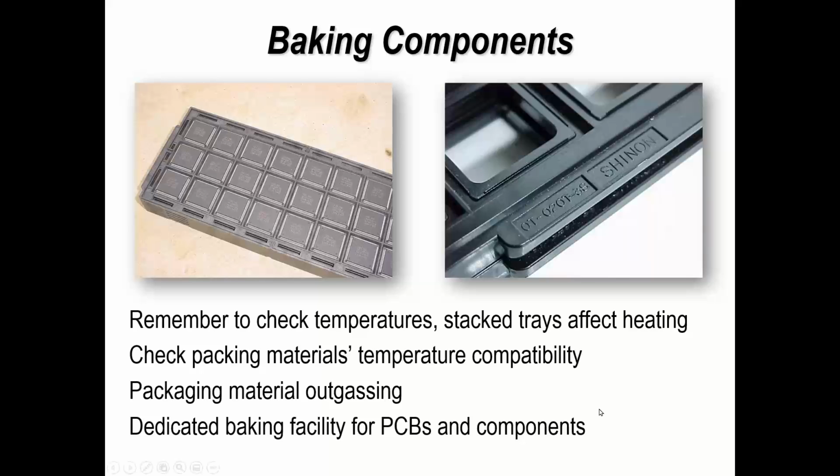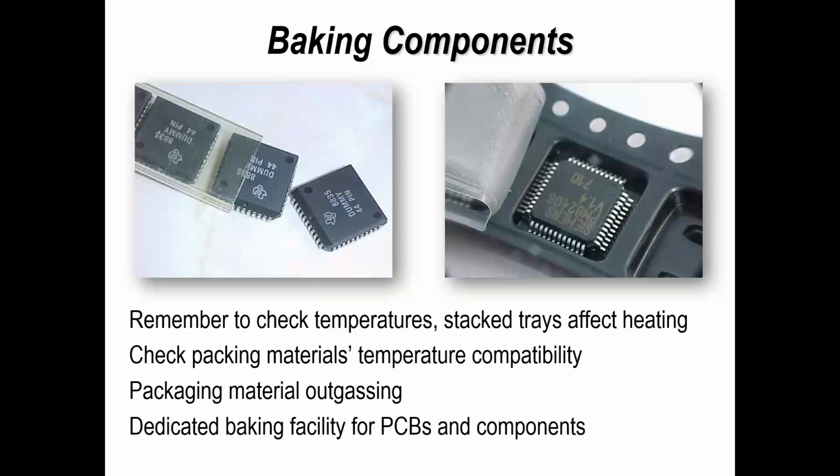So you're using it as a dedicated oven. You're not using it for anything else, like curing conformal coating, for instance, or baking boards that have got conformal coating on. Just think about it: if you put your nose inside an oven and it smells bad, you get a feeling that something is being given off by the boards during the baking operation or the components or whatever else you're putting in there, and that might affect the long-term longevity of the solderability or wettability of the part.